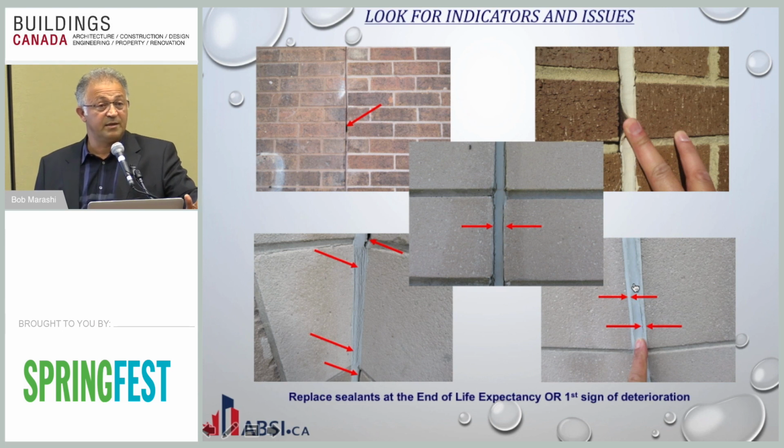You've got to go back to the slide we had, do a little cut test and see what kind of wall system you have. Are there brick ties? I mean, you can go and look at your wall and there's no brick ties. You can do something about it before it's too late. But if you leave it for too long, you're going to have to replace all that wall.